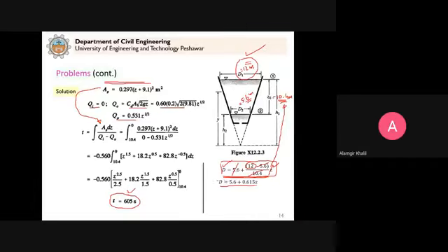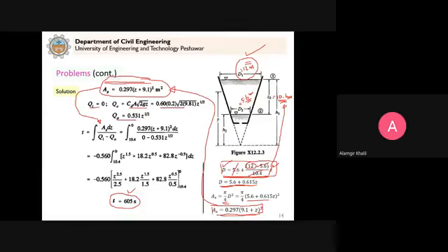So now we can express the diameter in this form. Now we have the area, which is pi by 4 d square. And now we get pi by 4 into 5.6 plus 0.615 z whole square. If you simplify, we get AS equal to 0.297 into 9.1 plus z whole square. You can see that this is essentially the same as this equation. So whichever approach is convenient to you, you can follow and you can get this answer.